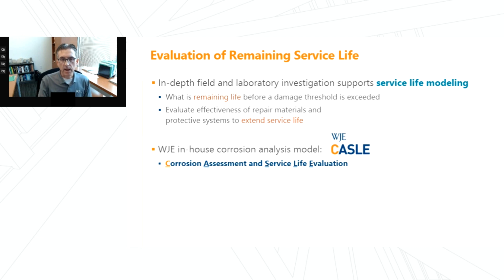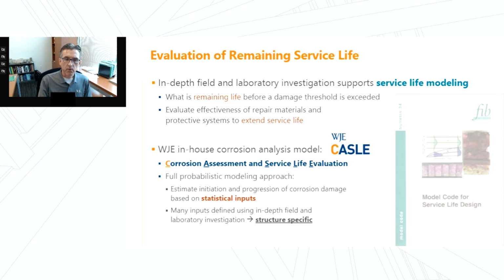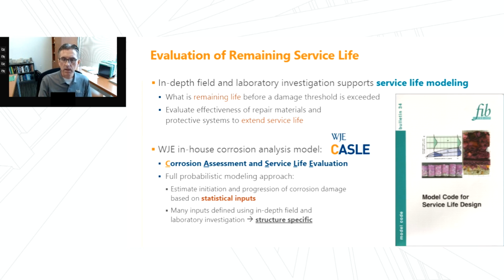At WJE, we have our own in-house model for doing corrosion analysis. It's known as CASLE, which stands for Corrosion Assessment and Service Life Evaluation. It is a full probabilistic modeling approach that's based on concepts that are in the FIB model code for service life design. We're able to estimate the initiation and progression of corrosion damage using statistical inputs.